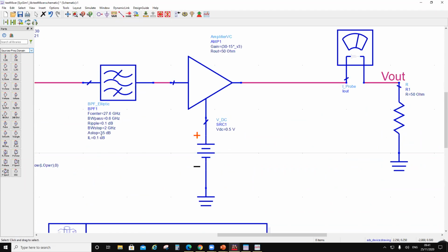So now there are no compression characteristics here. If this is doing 10 dBm out, then this will be doing 10 plus 22 and a half, so that would be compressing at around 32 and a half. That's what's going to happen. Let's give it a gain of 15. So now it is a linear stage, and this is not compressing. So 10 plus 15, it will compress at 25. So this output 1 dB compression would be around 25.